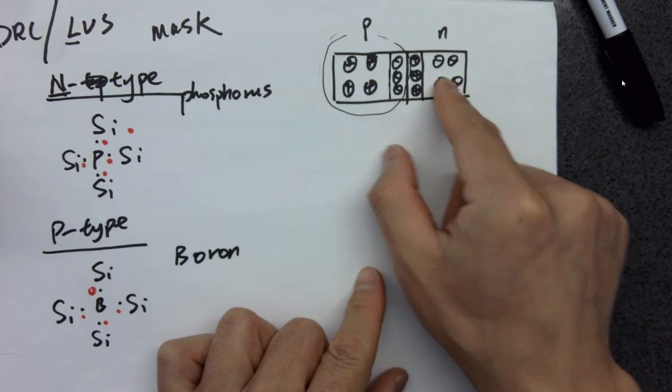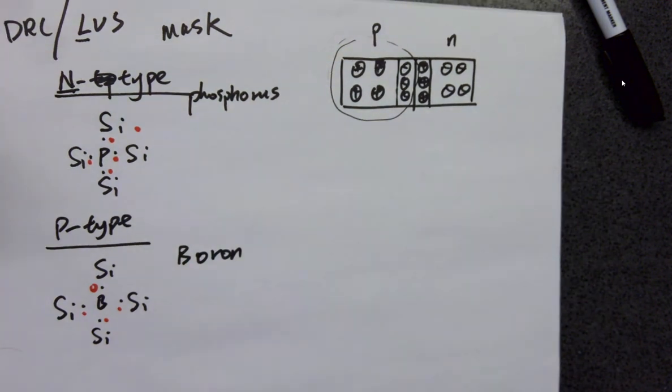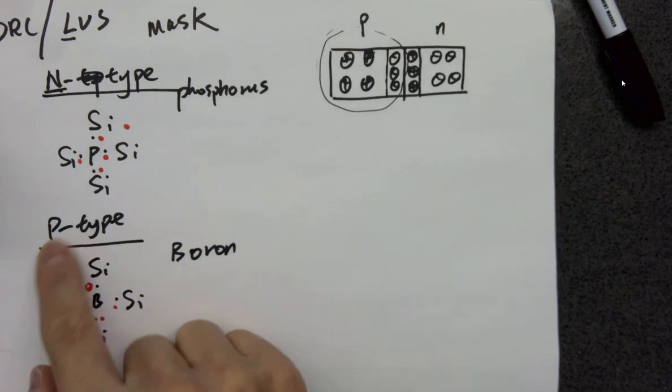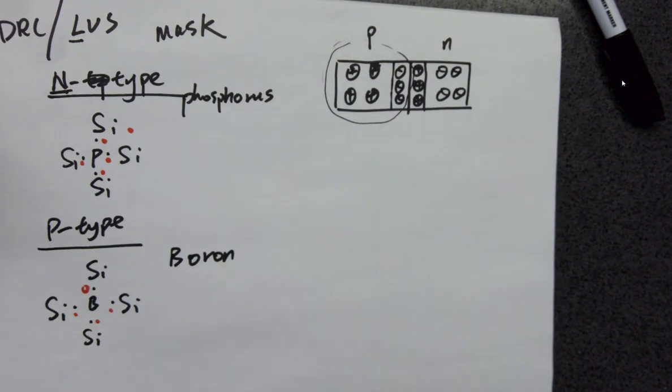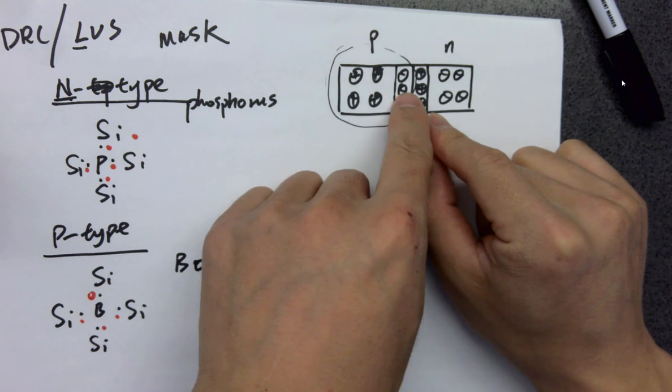It's the same concept for the other side. You have a neutral piece of material, which is silicon, and a neutral material, which is boron, and you mix them together, it should still be neutral because both are neutral at the very beginning. Even though they form a P-type, there are free holes, but still neutral. Just keep that in mind, still neutral. So that's why whenever there's a diffusion,